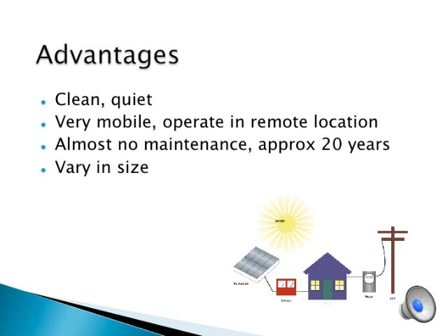The AC module connects an inverter to every single PV panel. It is the smallest grid-tied PV system. Each module can be configured and optimized individually. Ideally, each AC module can adjust itself to maximize output. Therefore, the system does not face series string problems and has a higher efficiency. Other advantages include being easy to extend or reduce the system and easy to replace modules. The main disadvantage is the relatively high cost since every PV panel requires an inverter.